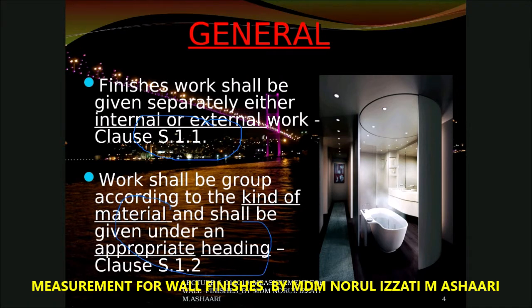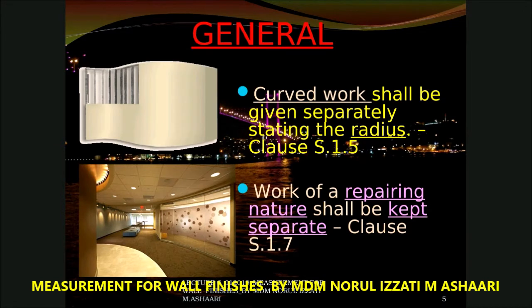So if you look at this photo, we are going to measure the finishes of this wall, either plaster or painting, or maybe plaster and painting, or maybe tiles and another type of material. For the curvature on plan, you also need to measure the curved material that is attached to it. So every time you see a curved wall or curve on plan, you must measure separately. One of the requirements is to state the radius.